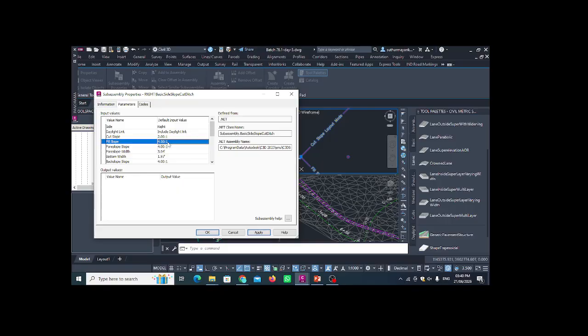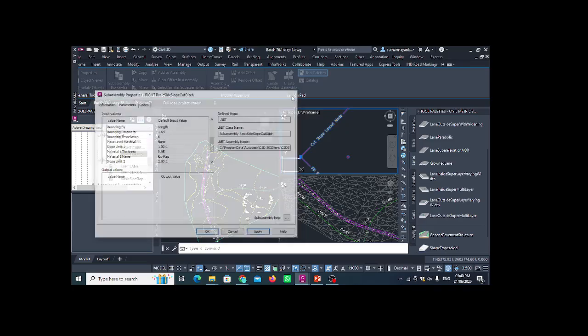Yes, sir. I think Ram Kailash ji asks about the types of soil: hard soil, hard rock, medium rock, soft soil, or ordinary soil. For different types of soil, the side slope is required accordingly, like 1 is to 4.